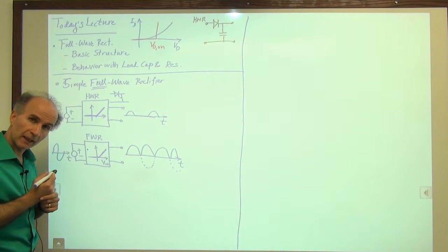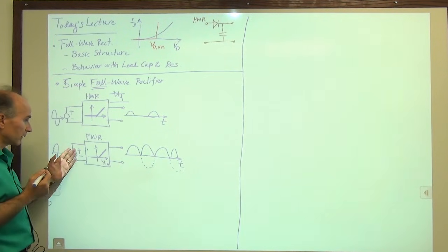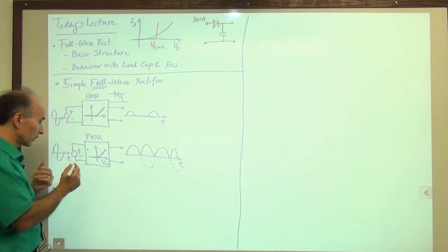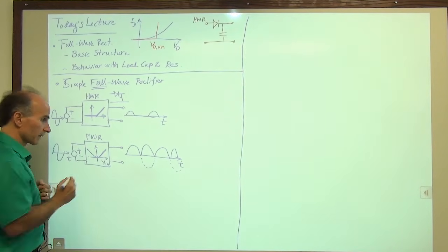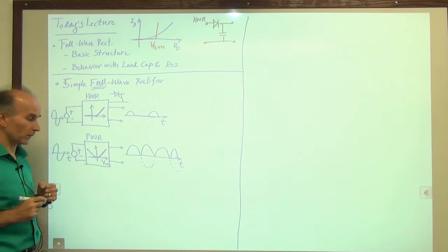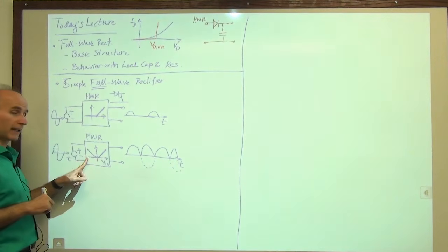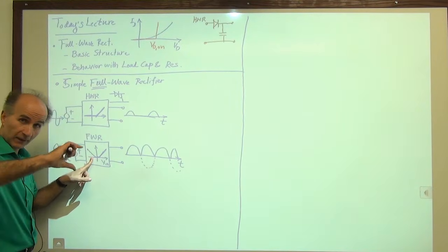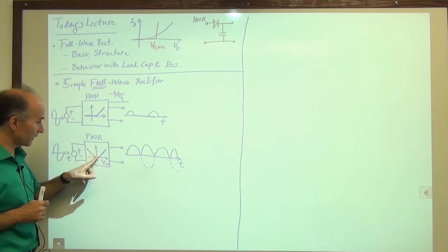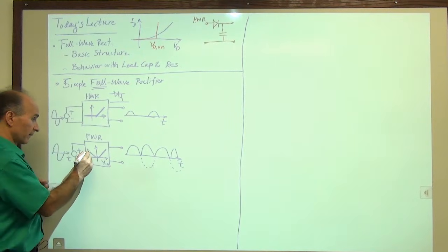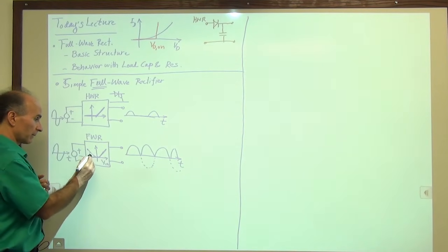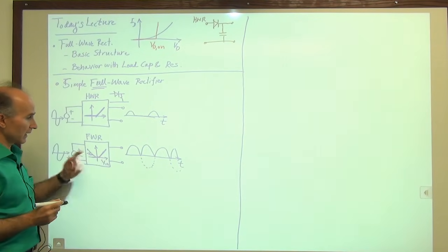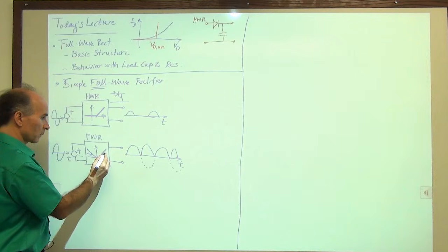So what we are thinking is that the input-output characteristic of this full wave rectifier should be something like this. Right? We see that if the input is sufficiently negative, we generate an output which is the same as the input except that it's flipped in sign. The slope is still minus 1. Maybe, right? We don't know yet, but maybe minus 1. And then this side is the same as before, so the slope is plus 1.